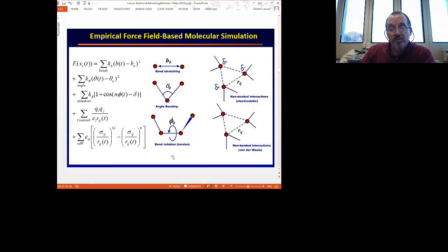If these parameters are all set to represent properly how the atoms interact, you can apply this to both all-atom and coarse-grained modeling to scale up your system to a very large degree, and all the atoms in the system should be interacting with each other appropriately. The downside of this method is that if your parameters are not set right, you can still run your simulation, but the results will have nothing to do with reality. So a key issue in these force fields is to make sure you have the force field parameters set properly to represent your system accurately.